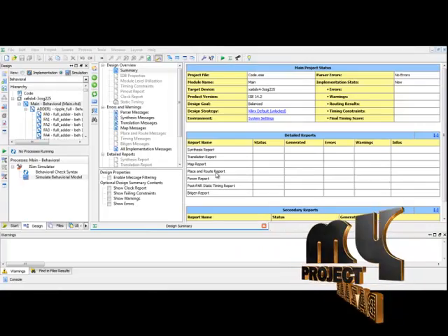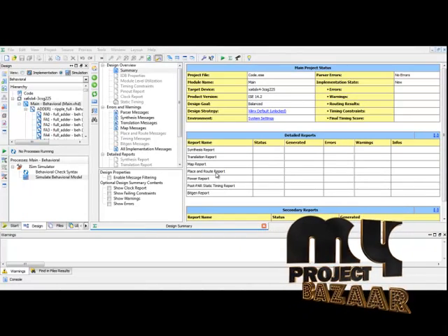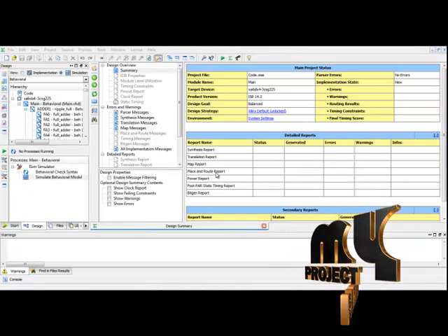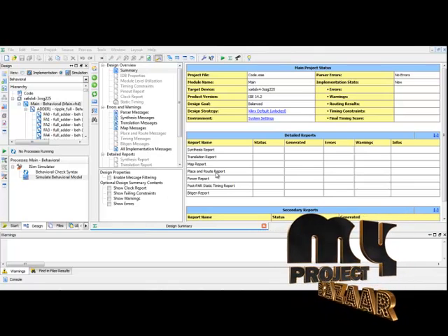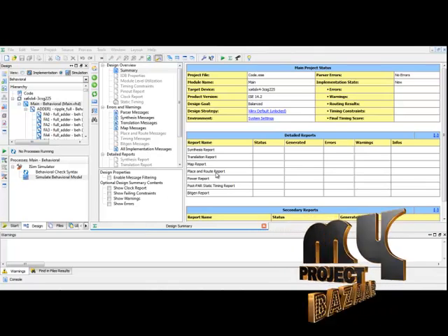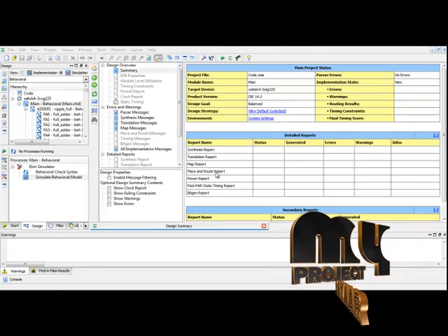Here we are going to discuss the running procedure of our project. In this process we have four steps. First step, we check the syntax error. Second step, we generate the RTL schematic diagram. Third step, we generate the technology schematic diagram. Finally, we generate the simulation waveform.